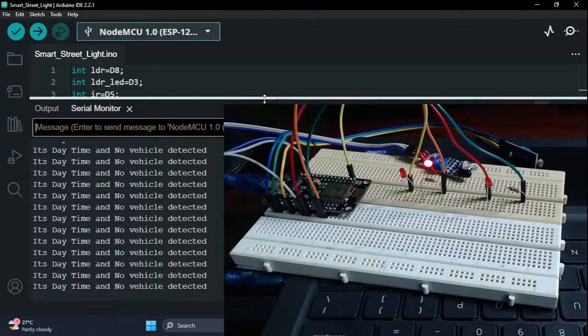Thank you for the response. So if you face issues like this, just disconnect all the things and connect it again, or you can close the IDE and reopen it again and upload it, or try to upload it again also. Check your port first. Connections, yeah.